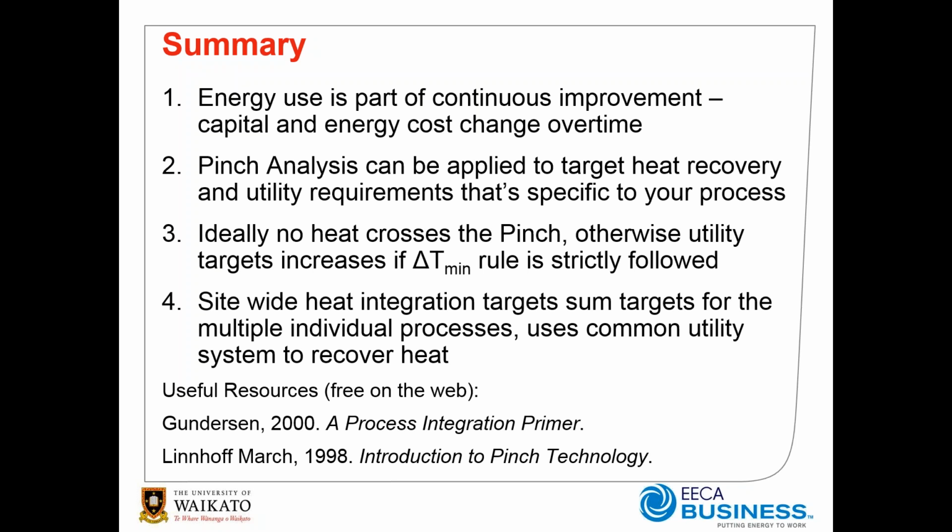In the ideal scenario, we should limit and eliminate, if possible, any cross-pinch heat transfer that occurs. If you don't do this, and you strictly follow the minimum approach temperature rule, then it is thermodynamically impossible to meet that target, and you have to increase the amount of utility you use.